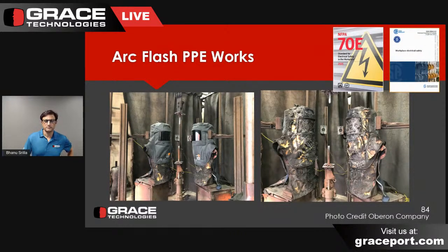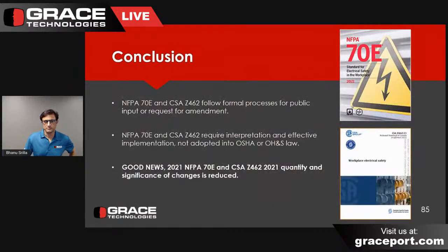So this was cool stuff, right? And it works. Arc flash PPE works. So the first thing is we need to get it on workers, and then we need to have the right PPE based on incident energy analysis or the category table method.